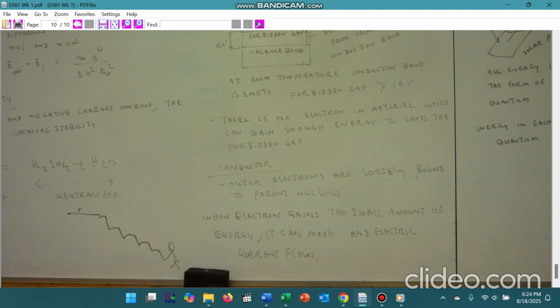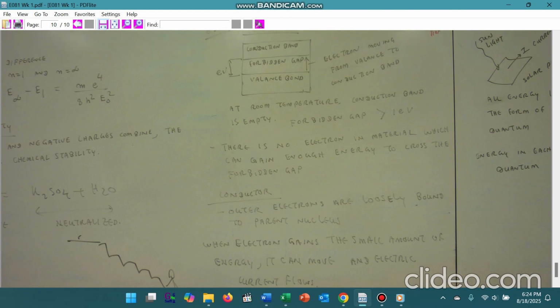So building L is similar to the conductor. You switch on the lift and then you can reach the top floor. But building K is similar to the insulator. To reach the top floor level, you have to climb up. This is the energy gap. This is the forbidden gap that prevents electrons from flowing. The forbidden gap energy level is very enormous for the insulator. It is very difficult for electrons to pass through from the valence band. So the forbidden gap is very strong.